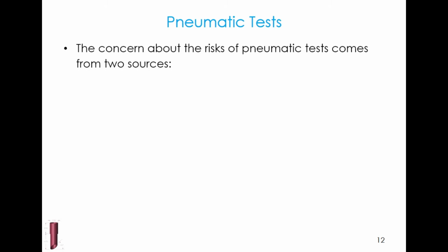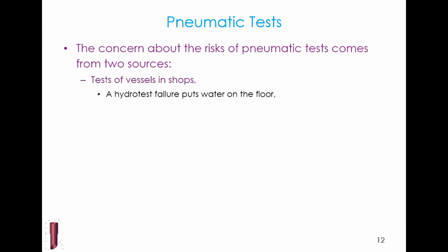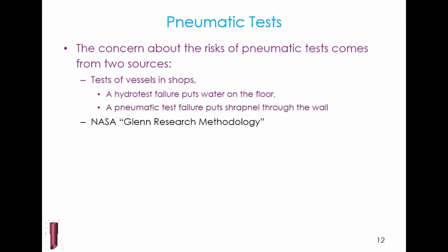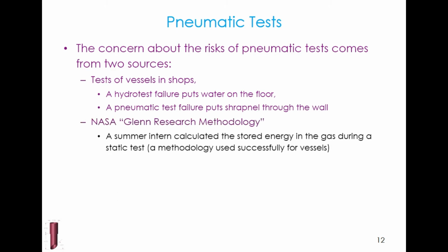Well, the concern about risks of pneumatic tests comes from two sources. Test of vessels in shops. Hydrostatic test failure puts some water on the floor. A pneumatic test failure puts shrapnel through the wall. And then there's the NASA Glenn research methodology.